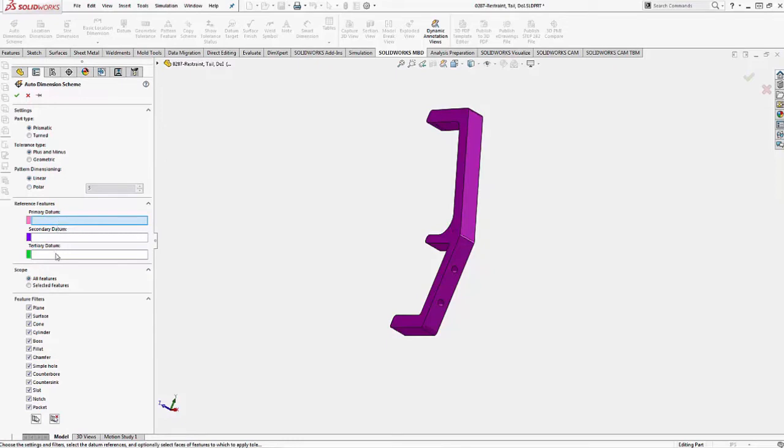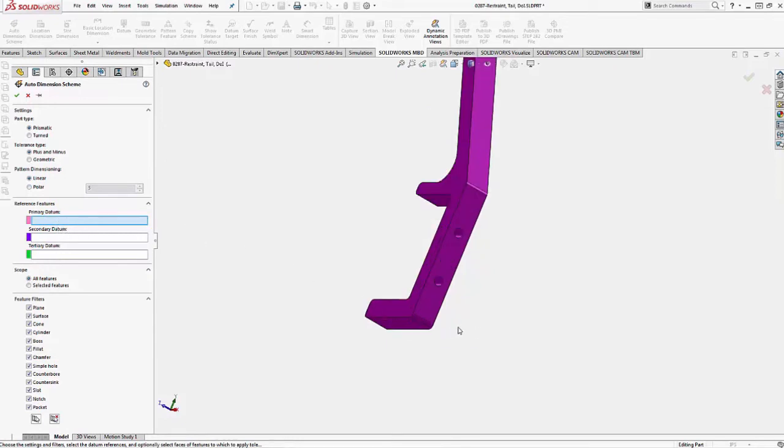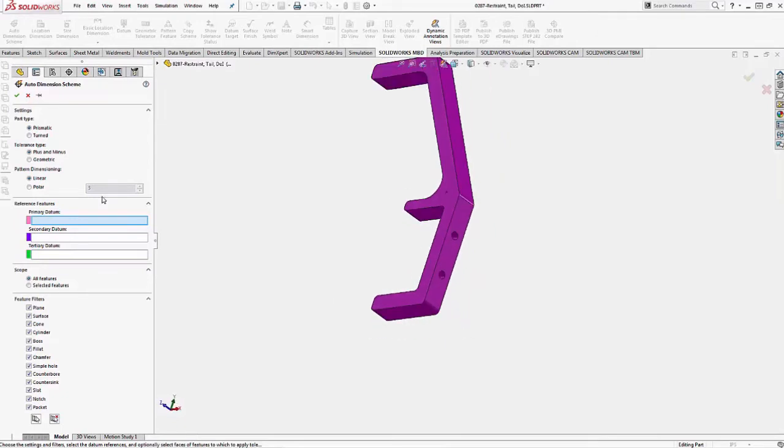Right here, we're going to establish some datums. Datums I'll go over more in depth when it comes to GD&T; they have more of a significance there. Right here, when we're identifying datums, we're more so just identifying zero points, like an origin or G54 for maybe a machinist out there. Where are dimensions referenced from? Where are the critical anchor features, if you will?